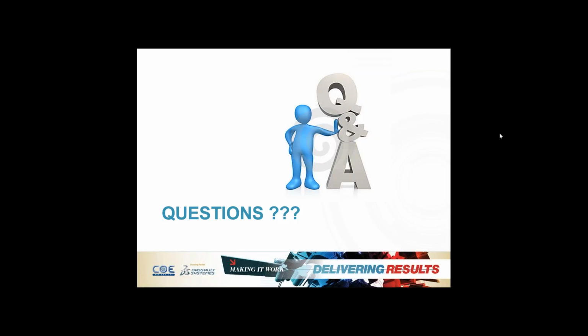Corey is asking, how did you get the scan to import at the absolute origin in CATIA? Francois? From our solution, using our scanner, there are some alignment tools that are available to the users from our own software called VX Model. So basically, you can do the alignment there, and that's how we got the mesh file to be already aligned with the absolute origin XYZ. So basically, we've created features such as cylinders and symmetry planes and all stuff like that, and then we align the mesh correctly to this referential. Otherwise, there are other tools available in CATIA also to do the alignment.